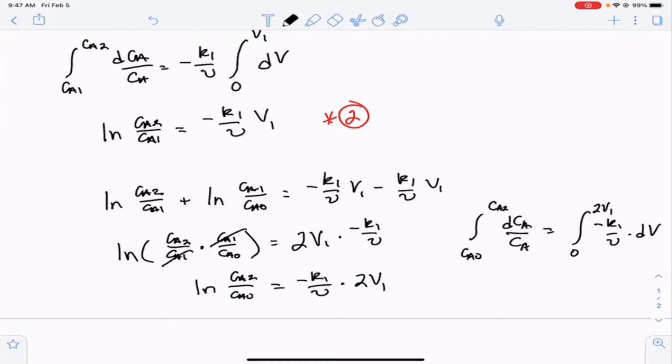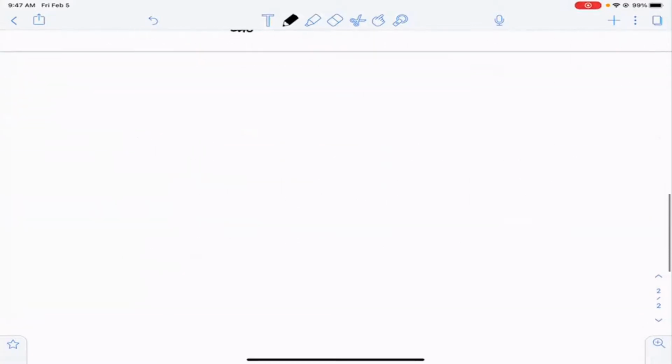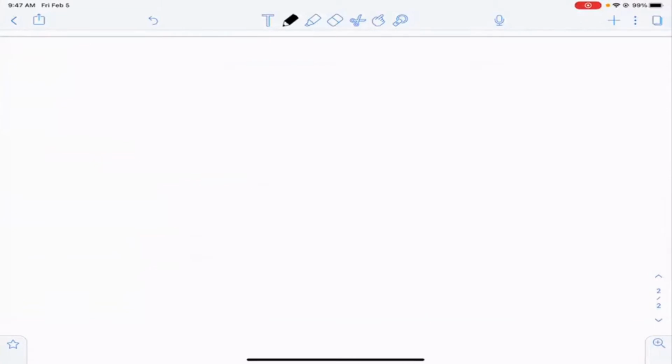You could have a bunch of parallel tubes that would allow you to increase capacity of your plant. You also, depending on the process, might put some plug flow reactors in series to help with maintenance, but you certainly wouldn't do it to increase conversion. So the much, much more common thing is to have PFRs in series with other reactors. And the most common configuration really is to have a continuously stirred tank reactor at the beginning, and then to have a plug flow reactor almost as a polishing reactor.